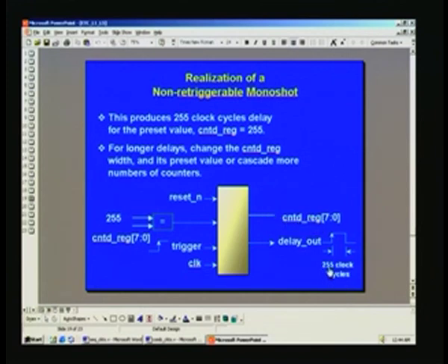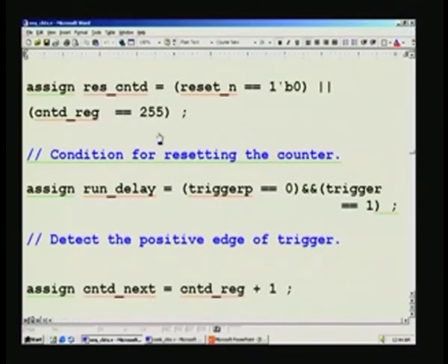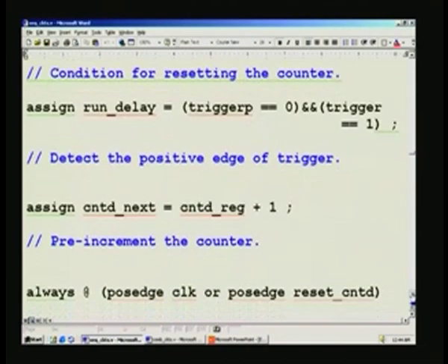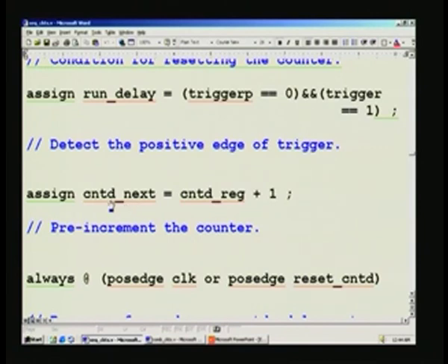And now you might have noticed this is the change I have made here, right. So, also here, and that is precisely what is written here. For run delay, we sense the rising edge here, and as usual we pre-increment the register here, and earlier I had used just CNT, I have renamed it as D, right, to indicate it is the delay that we really want to do. So I have just renamed it, because otherwise that earlier counter will be overwritten by this, or this will be overwritten by the other one. So, we can't predict that.